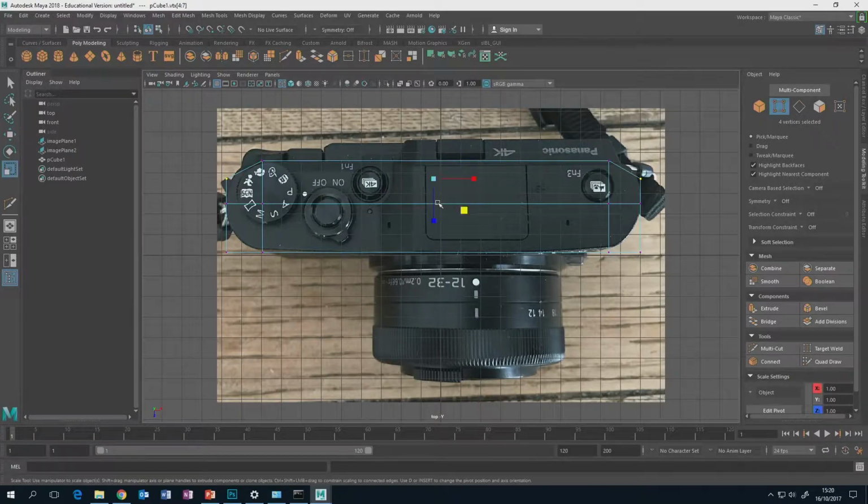and then I'm going to scale them, press R. I'm going to scale them just in one axis, because if I just scale on one of these handles, then I'm only scaling in the X-axis if it's red, Z-axis if it's blue, and you can't see it, but the green one would be Y. If you scale it from here, then you're scaling it in all axes. If you're scaling it here, you're scaling it in just two axes. But if I just want one axis, because all I want to do is just bring these points inwards a little bit, I'm just going to scale these in a little bit like that.